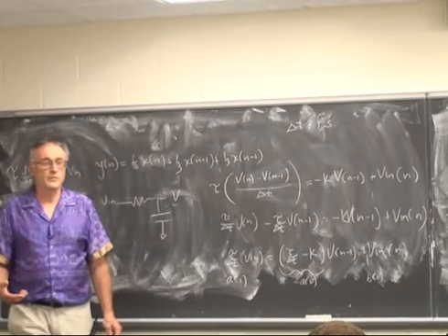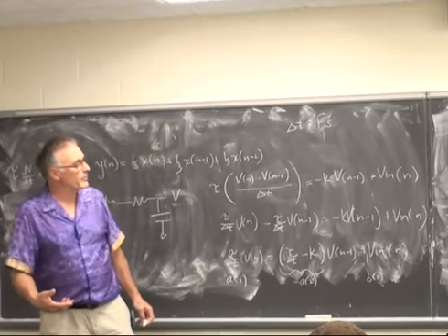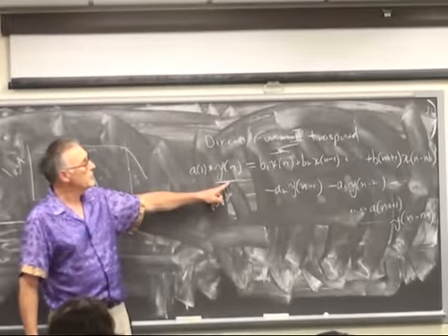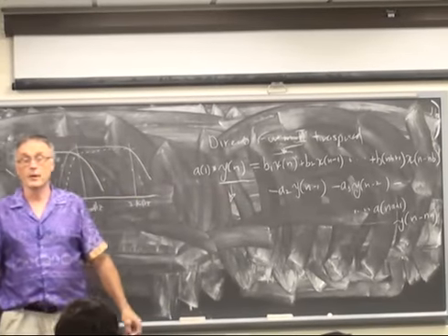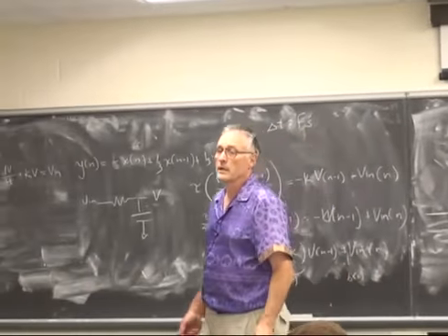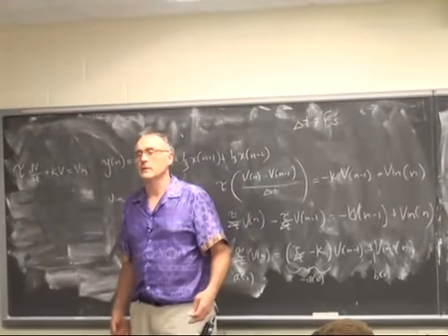If you wanted to build a software radio that ran at 10 megahertz, then you would not be able to implement this equation in software running on a CPU, but rather you would implement it in parallel, running on multipliers and adders instantiated in hardware. I do want to talk a little bit about that.